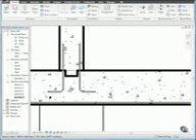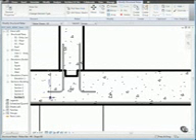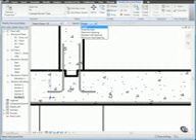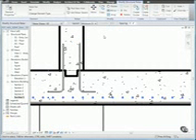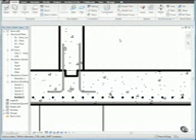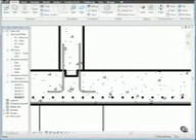Select the single rebar, and on the Options bar, for Layout, select Minimum Clear Spacing, and with the spacing at 4 inches, press Escape twice. Then, close the file without saving it, as the next lesson will provide its own training file. And that concludes this lesson.